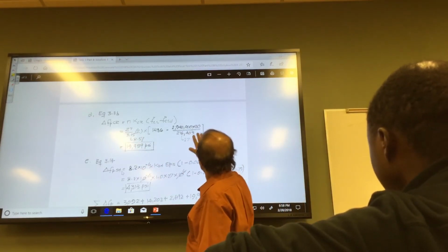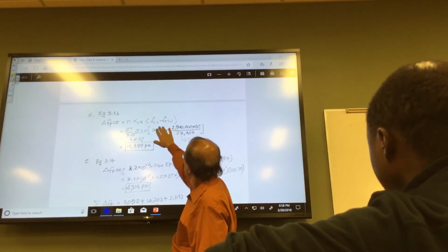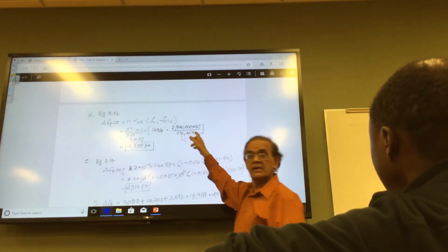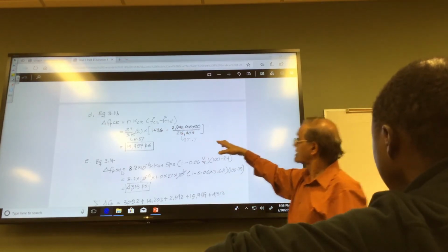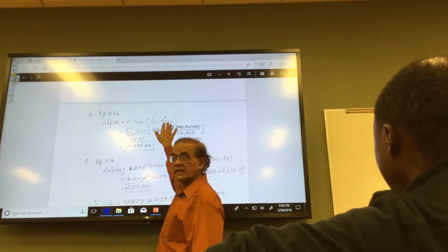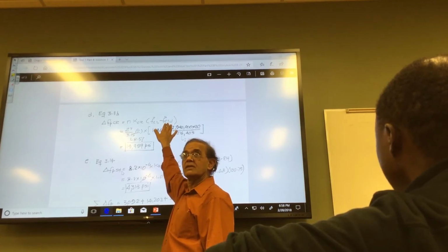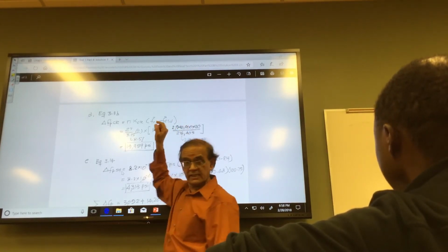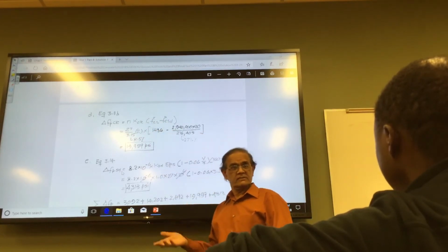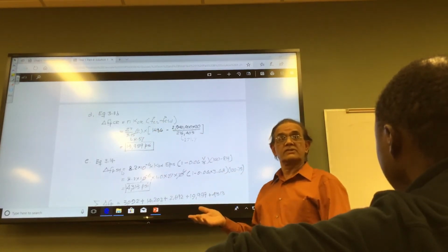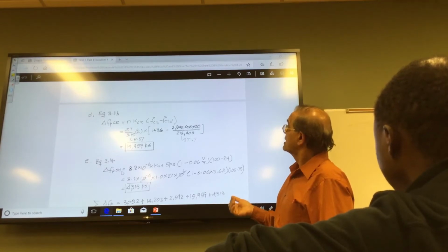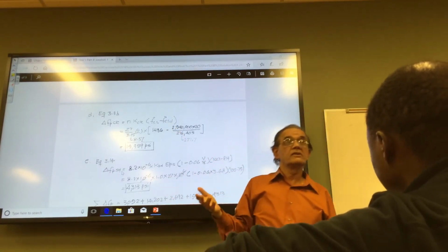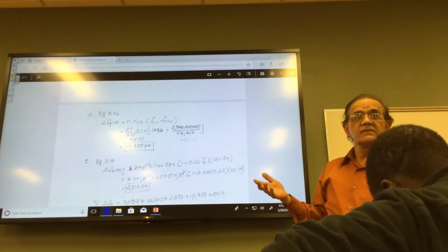And so FCS minus FCSD. Now, somebody could explain to me why we are subtracting from this to that? Anybody? Why are we subtracting this FCSD? FCSD is stress caused in concrete, because it says C. SD is the superimposed dead load, right? So the reason for that is